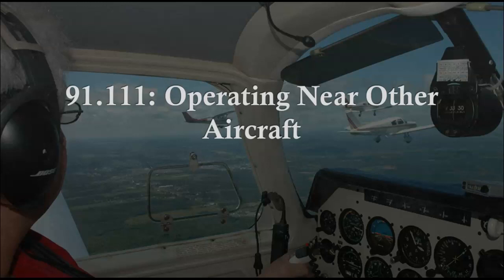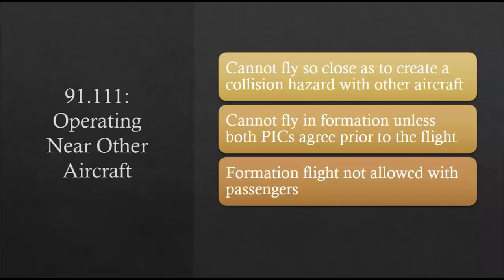Federal Aviation Regulation 91.111 is about operating near other aircraft. There are specific rules for operating near other aircraft. This applies to pilots who are planning on doing formation flying. 91.111 states that you cannot fly so close as to create a collision hazard with other aircraft, and you cannot fly in formation unless both PICs or all of the PICs agree prior to the flight. Formation flight is not allowed with passengers.